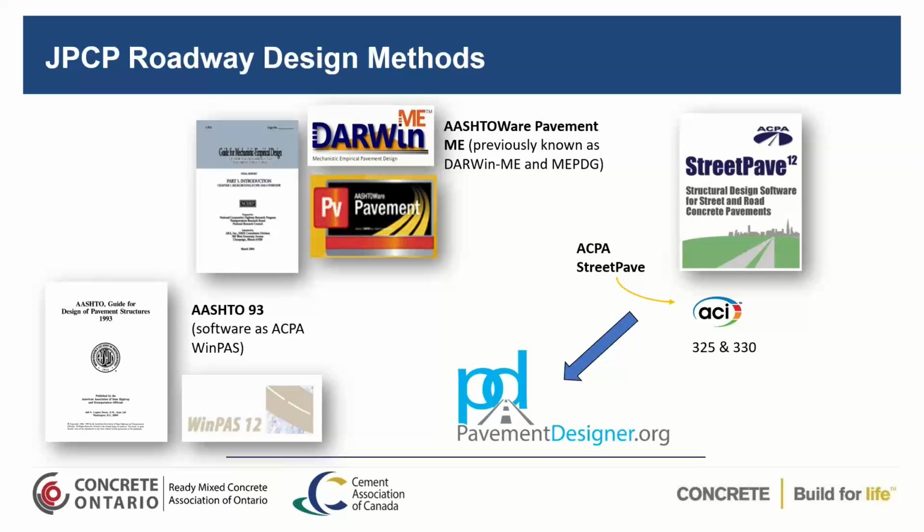So when you're looking at pavement designs, there's a lot of different methods out there. The AASHTO 93 design procedure is probably one of the most common ones that's been used. Developed by AASHTO from the road tests that were done, this is really an empirical design procedure. They ran the vehicles around the track. They had the ESAL loadings that they did for that. And then they had different pavement designs, and they analyzed the distress of each pavement design that was being driven over. Very good, detailed information, but it is empirical data.